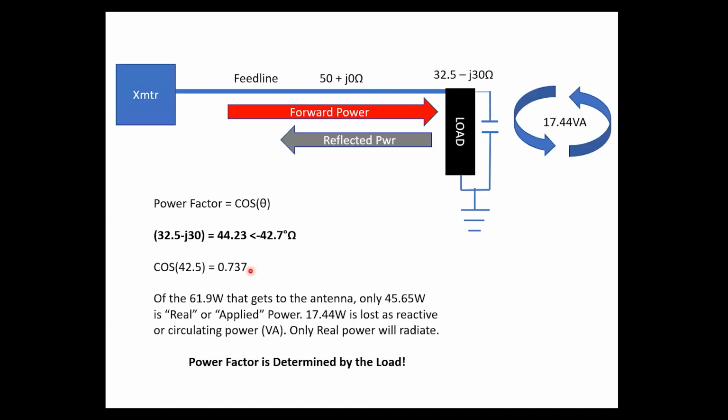So here we've got one that we worked out the last time, where we've got a transmitter with 100 watts coming out of it. I think we had 100 feet of RG8 here. And at the particular frequency we chose, I think it was 1.36 dB of loss. And that means that we lost all but 73 watts to this point right here. That was just basic losses in the transmission line.